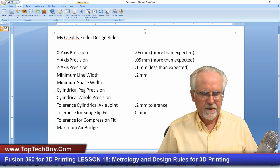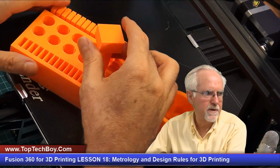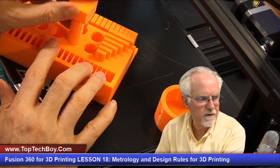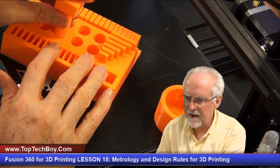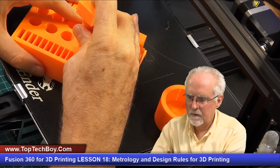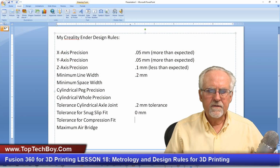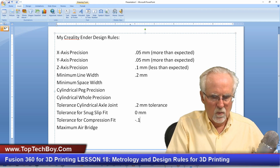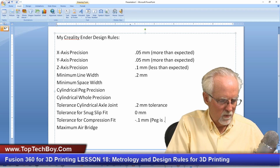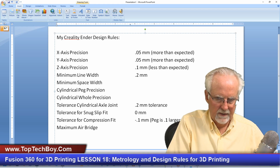And now for a compression fit, I have to be careful doing this because I don't want it to really become a compression, because then I would lose this design. But clearly I can get that out. If I come here to 14.9, I think I could get it out. But here I can't get it in. So about 14.9 is where I would get a compression fit. The tolerance for a compression fit, I would say, is minus 0.1 millimeters. So that would be peg is 0.1 larger than hole, like that.